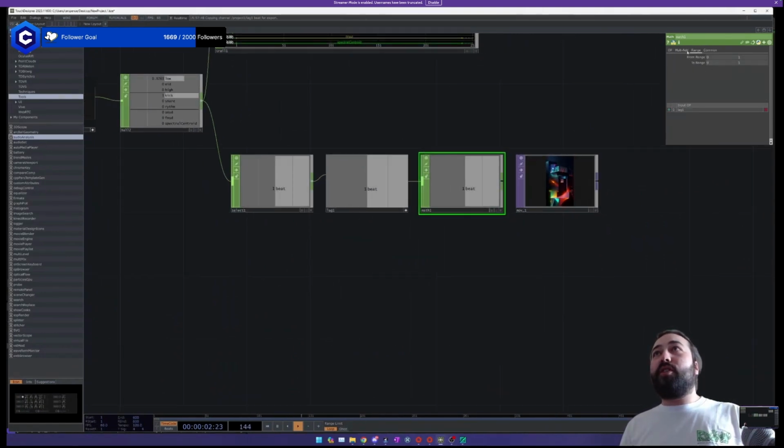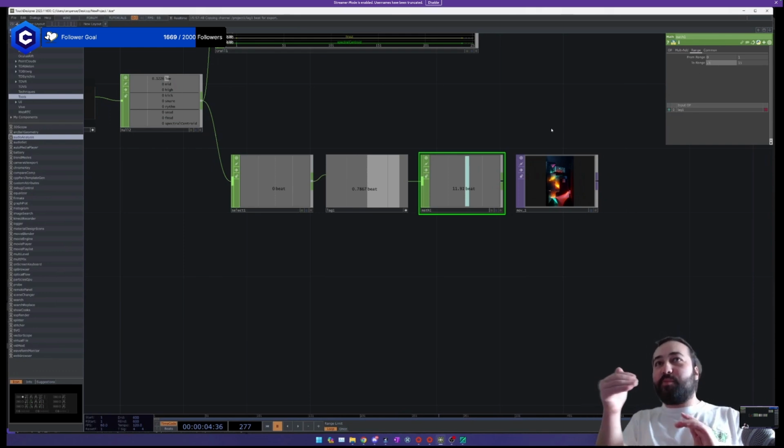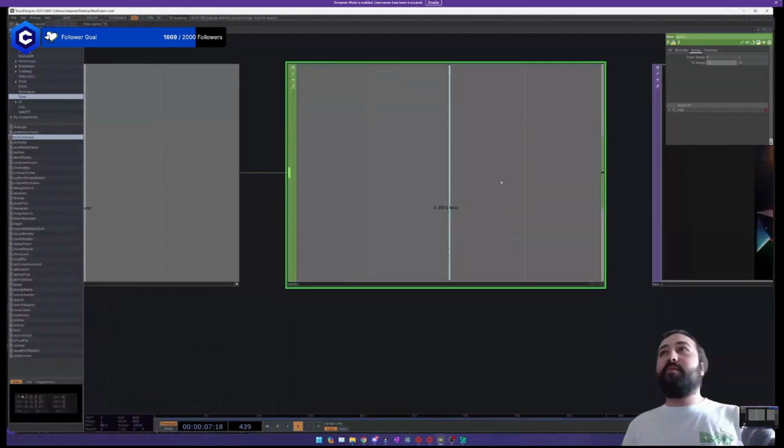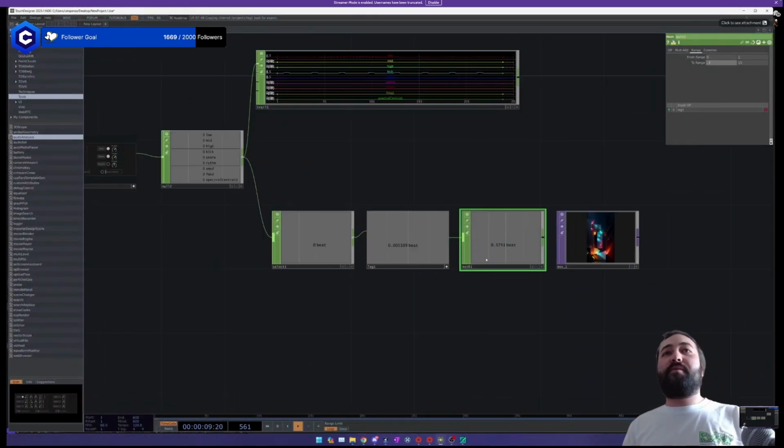And we're going to go to the range tab. And so we can say, instead of going from 0 to 1, we're going to have you go from 0 to like 15. And maybe instead of starting at 0, we'll do 0.1. So that's always kind of moving a little bit. So actually we'll do 0.5. So it's always kind of moving and then just speeds up just for the kick there. So you see now it's going between 0.5 and 15.